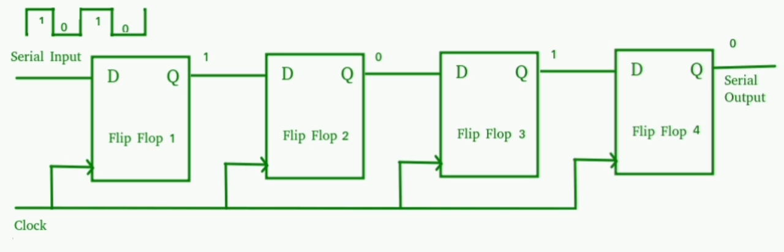State table. A state table expresses system behavior and consists of the present state, typically given in binary encoded form. Inputs, the external inputs used to cause state transitions. Next state, the state which occurs after transition, expressed in binary encoded form. Output, which occurs other than the state. Note that there would be no outputs in a Moore machine.